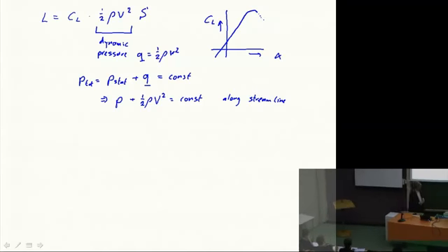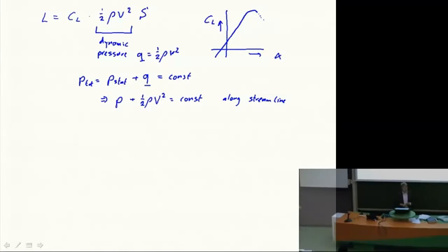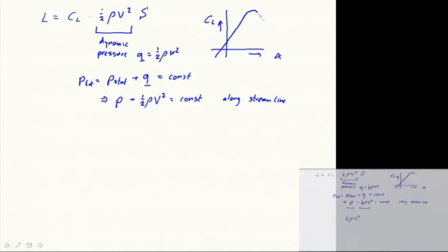It's also often used to capture everything in one, but the pressure is not really easy to imagine. So putting a number to this doesn't often give you a good feeling. So what we often do is say, if we have a certain dynamic pressure with the true airspeed filled into the equation, I can also say, well, this would be equivalent to flying, for instance, 200 knots at 10,000 feet, which feels, because of the thinner air, equivalent to 150, for instance, at sea level.